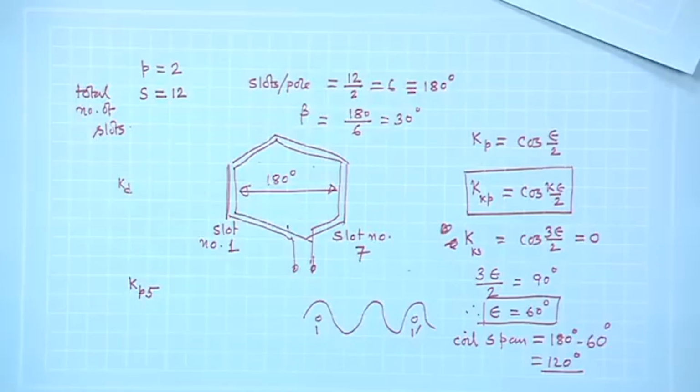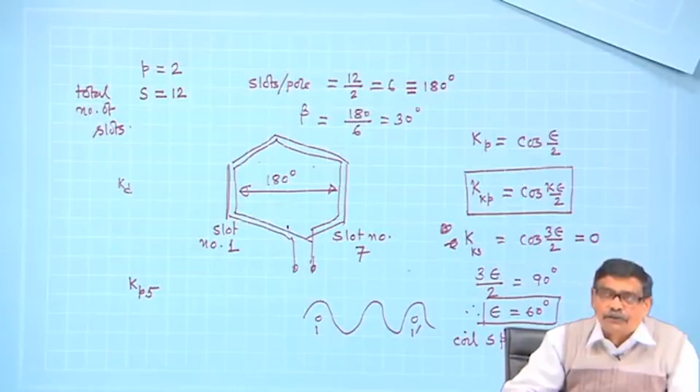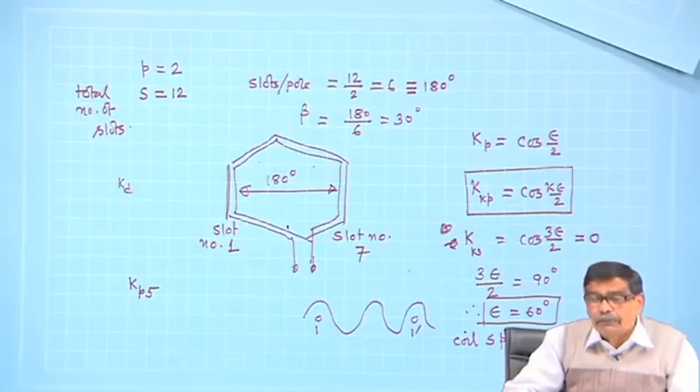We will see in a 3-phase machine, line to line voltage, even if third harmonic voltages are present in the coils, they do not appear in the line to line voltage. So, maybe at that time you will be interested to nullify the fifth harmonic voltage.